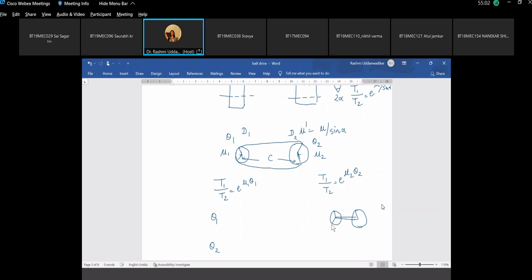This will be the overlap here. For the larger pulley, the overlap is larger. Here, if I consider this angle as some angle phi, then sine phi is (d2 minus d1) by 2c.